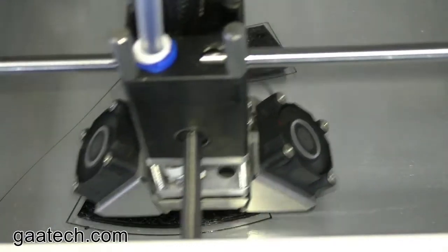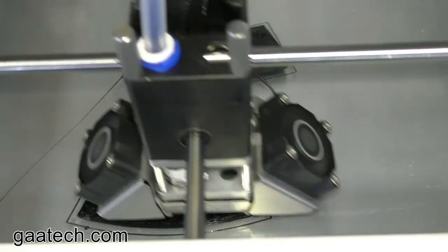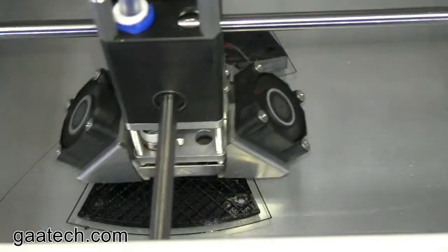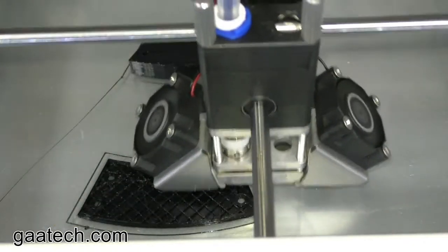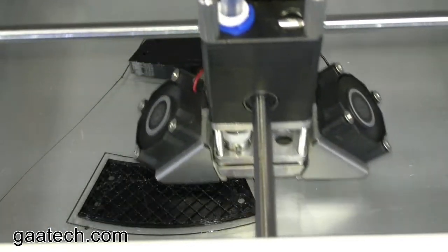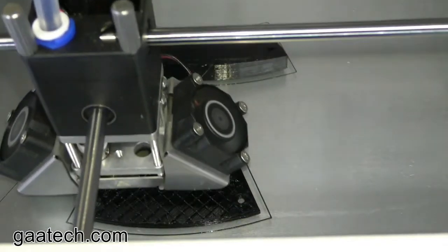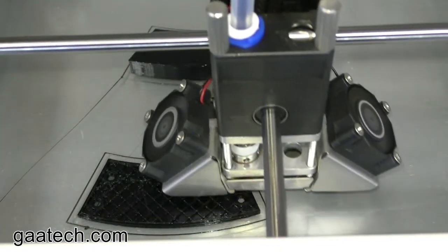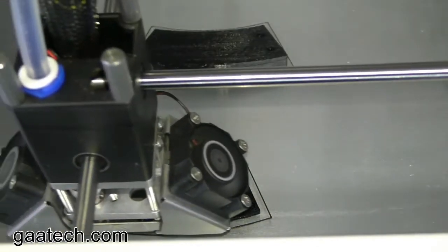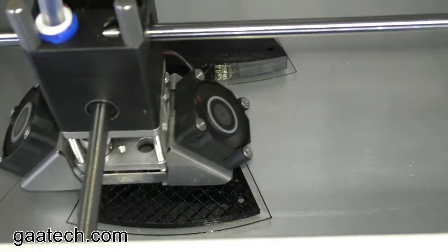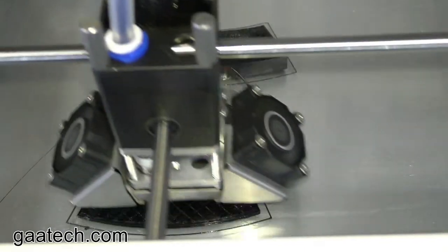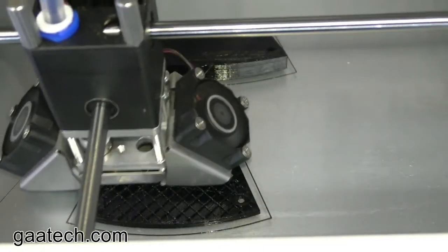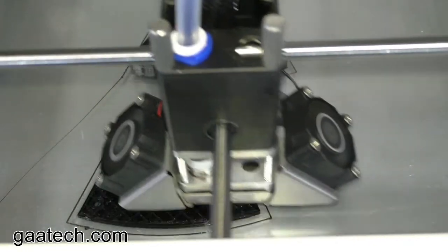Although they look the same, it's going to be used to sandwich a mini quad arm together. So one of the mounts goes onto the aircraft, then the arm is going to go on, and then the top mount will go on. And the reason these are required is so that the bolts driving through these two mounts, the body of the airframe and the arm, can go at 90 degrees through all the parts.